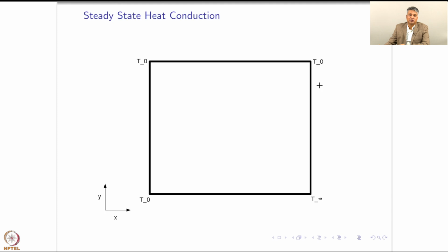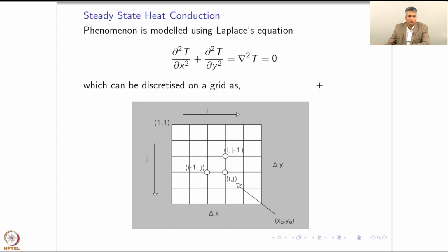So first of all, we need to write down what the laws of conduction are. We also need to make a few assumptions. One of the first assumptions that we will make is that the plate is of uniform material and hence has uniform thermal conductivity. It's quite possible that the square plate, even though it might be of the same material, could have voids, could have fractures, could have different thicknesses, could have some material anomalies which cause the thermal conductivity to change within the square. But we are taking a leap of faith here, saying that the material is fairly uniform and the thermal conductivity is constant.